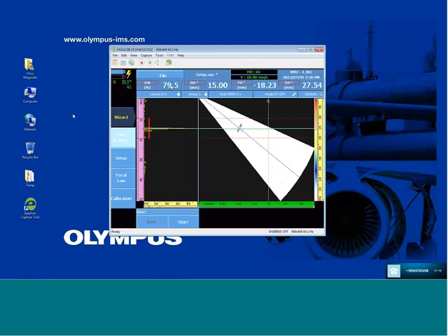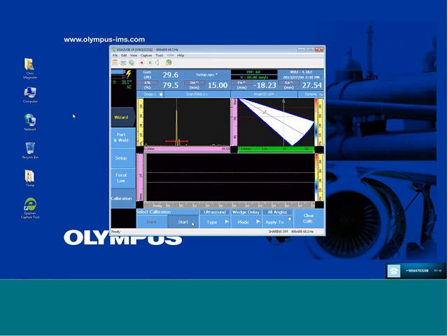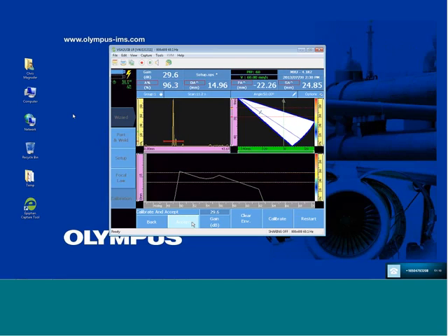So what I'm doing, I'm accepting the calculator's values for wedge delay because I've verified manually that my setup is in tolerance. Generally, that's much preferable than making an empirical measurement and downgrading your wedge delay. Now, if the wedge is really worn, then of course it's going to reflect that in the calibrator.